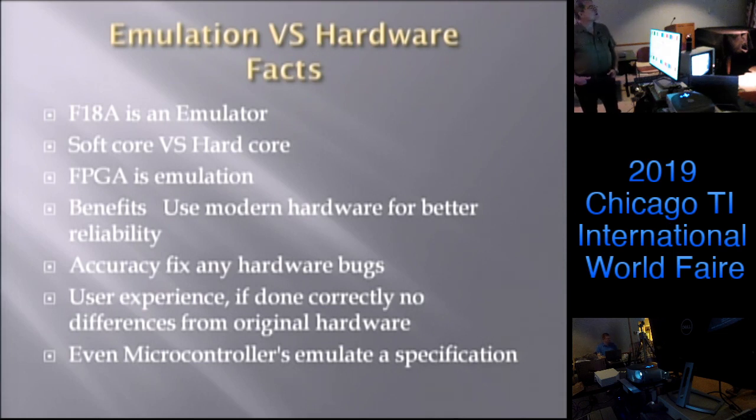So emulation versus hardware. A lot of people like the real silicon. The problem is that the real silicon is getting old and it's more failure prone as time goes on. Additionally, capacitors degrade over time, and on the power supplies of a lot of the real old consoles, just to prevent failures, you might want to think about replacing the capacitors.